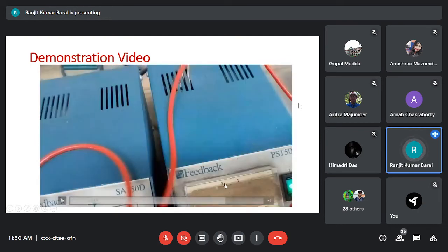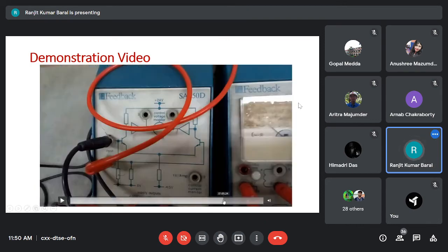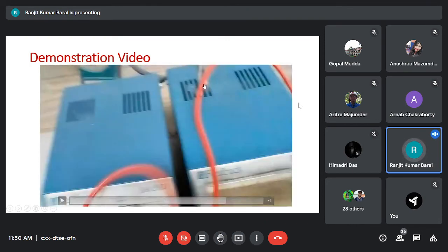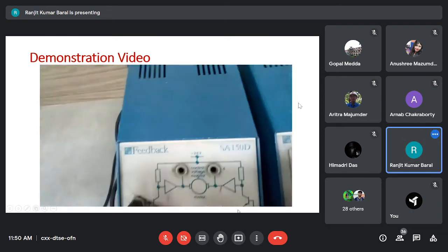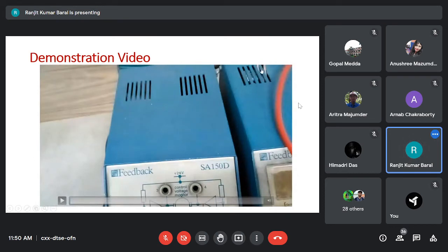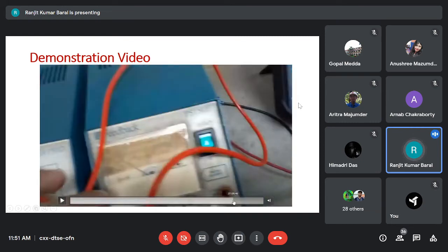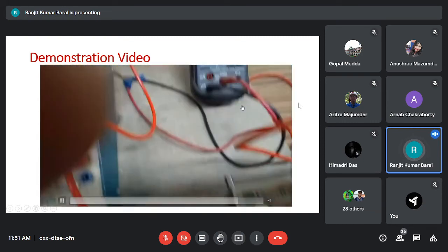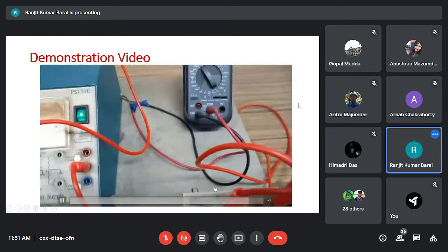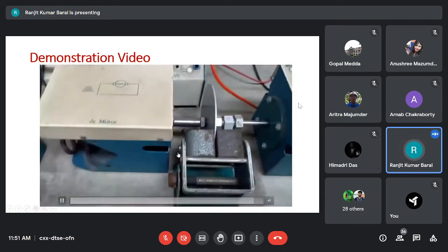Because the scale was not very good, we have bypassed this ammeter and taken two wires. Just the terminals were visible from here. You can see a bit hazy. Can you see two conductors have been taken out from here? They are actually to bypass this ammeter, and we can measure this armature current by some external ammeter, a multimeter in ammeter mode, in a precise manner.